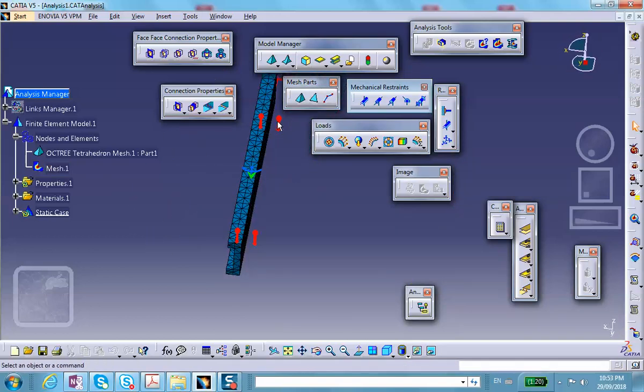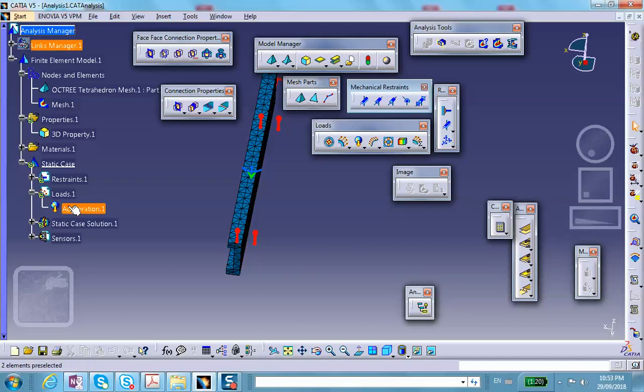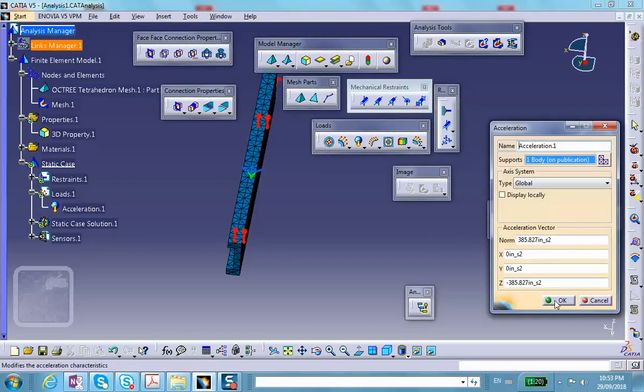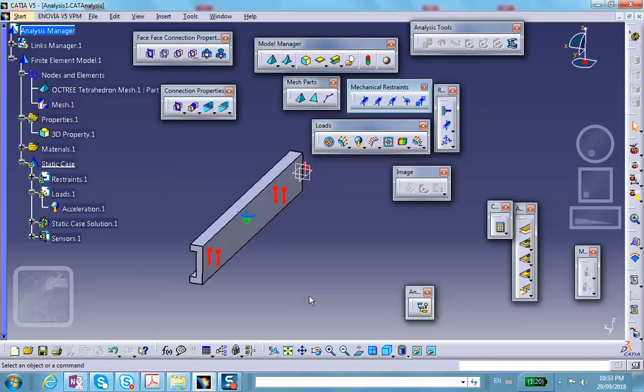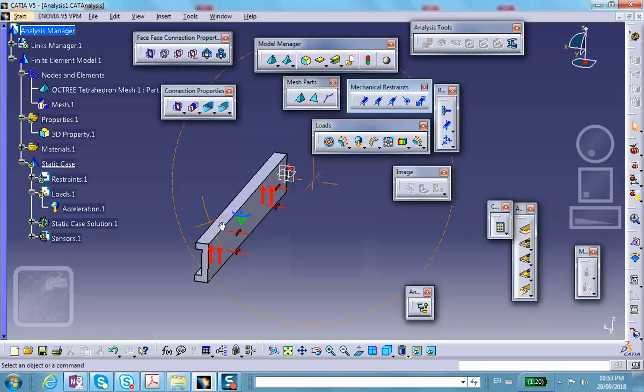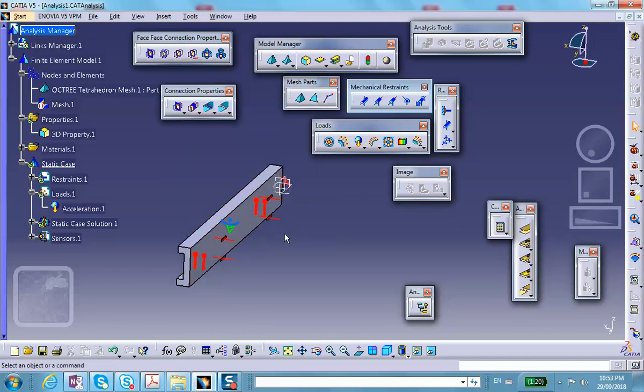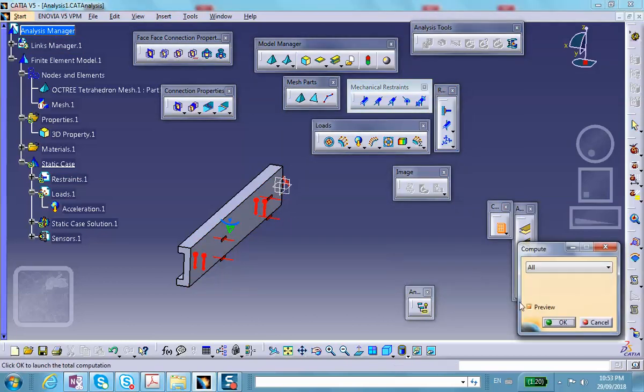Well, first of all, you see that this residual is because we already had the right-hand side, which has now disappeared. Well, that's okay. If you go here, where is that, under the load, and just double click on it, it readjusts so that it knows that there's only half of the piece present. So let me deactivate my mesh. The only thing you have to do, and don't forget, this has to be a surface slider. Without it, there's a major point deduction. Okay, you don't just cut the object and pretend that there's nothing acting on that artificial surface that you have created. For the case of solid, the surface slider is going to represent that plane symmetry.